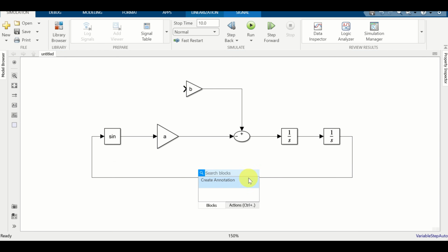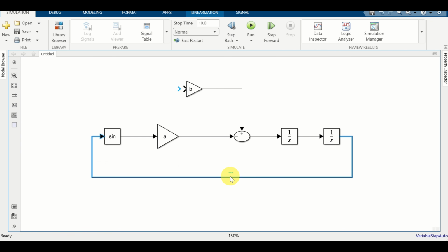And over here we can click on this block and type theta, and over here you can also do the same thing. You can type d theta. Okay, perfect. Now we have our dynamics. However, over here we need to enter the initial conditions. Namely, in our MATLAB parameter script, we have two initial conditions.